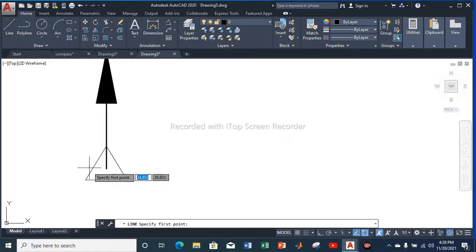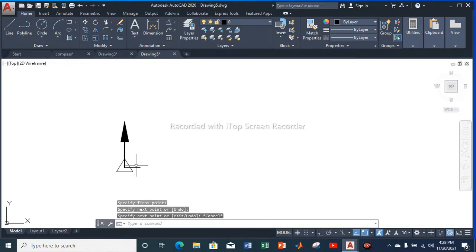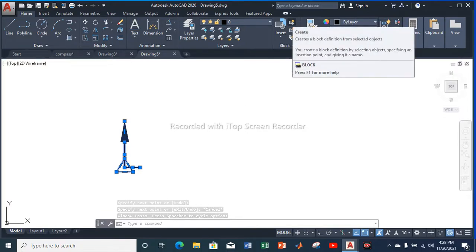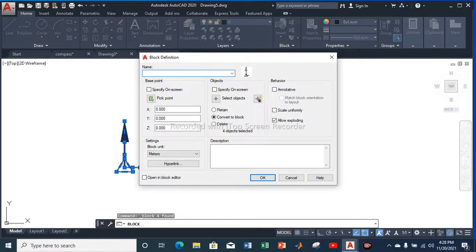What you need extra is, go to your endpoint, and draw a horizontal reference line. It's going to be a horizontal reference line for drawing our four bearings. You can draw it of any required length. So after doing this, select all these drawings, and go to a point over here. It says create a block, so click on it. Create a block. I'm going to name it station for now. And now go into pick point.